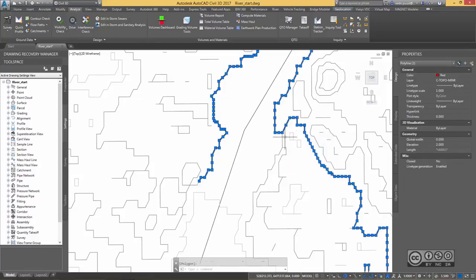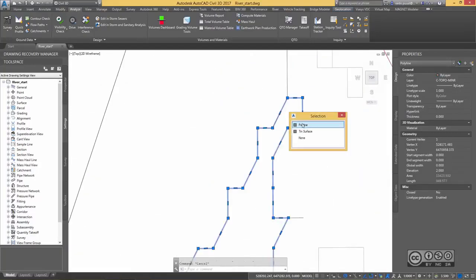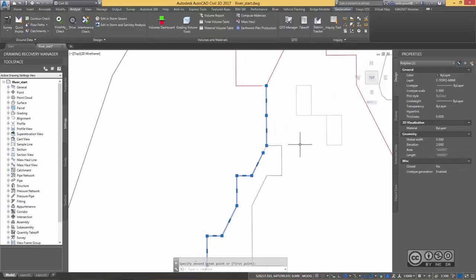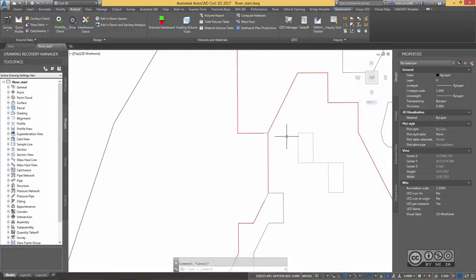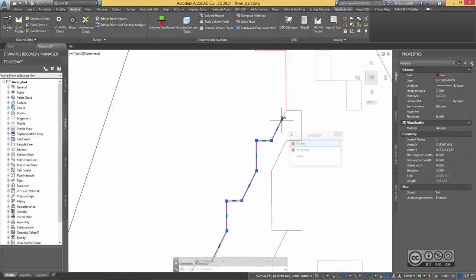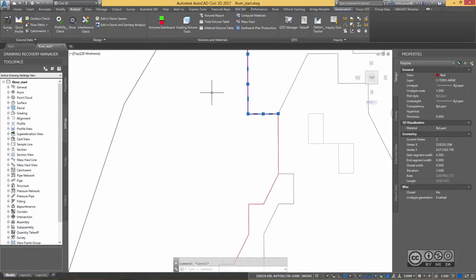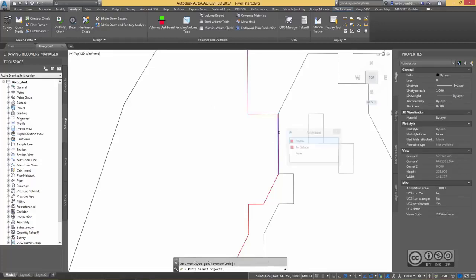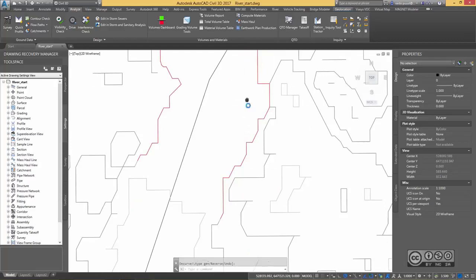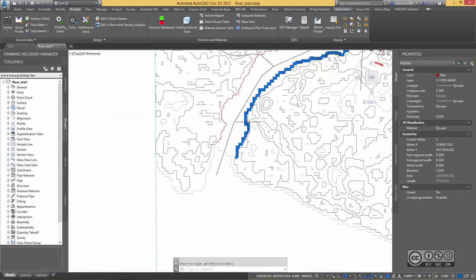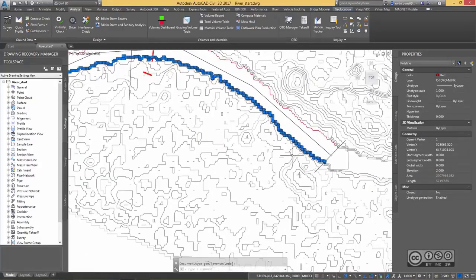So in here I need to break it again. I need to break this one and use some different color again so that it can be easily selected. I connect those polylines together and use a join command to join into one polyline. PE command again and select the 2 other polylines. Hit enter. And to be sure, just select it again and let's see if we have one continuous polyline on